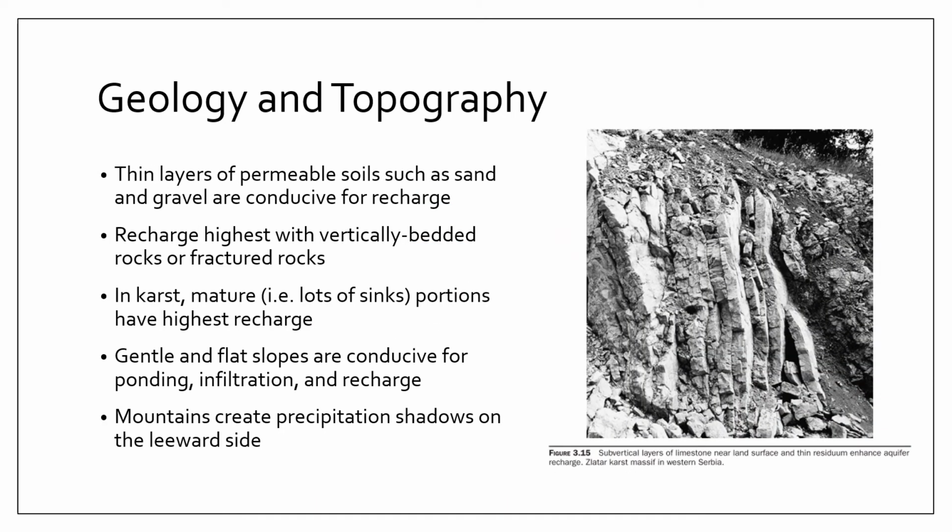Now, another factor for recharge is your geology and topography. As discussed before, it depends on the soil you have. If you have a thin layer of permeable soils like sand and gravel, they are conducive for recharge. But if you have a thick layer of clay, that will essentially block water from reaching your deeper surfaces.